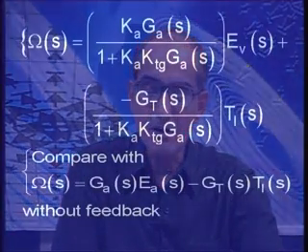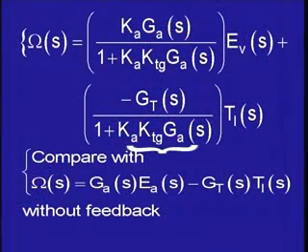So what has now happened is the following, and let us look at the torque term first, because that is the disturbance variable and we are interested in reducing the effect of the disturbance on the system performance. So let us look at that part first. Earlier it was simply GT, or with a minus sign, minus GT. Now it is minus GT divided by 1 plus KA K tacho generator GA, and this KA K tacho generator GA is simply the loop gain.